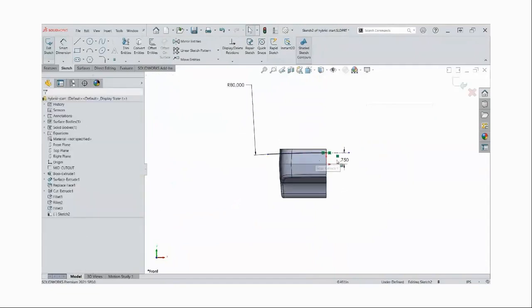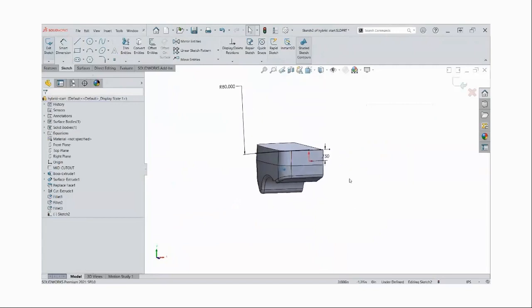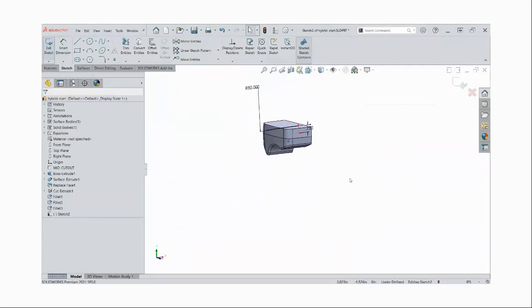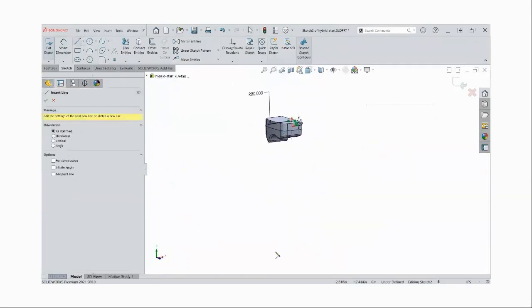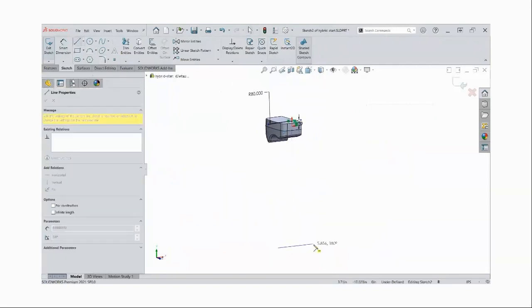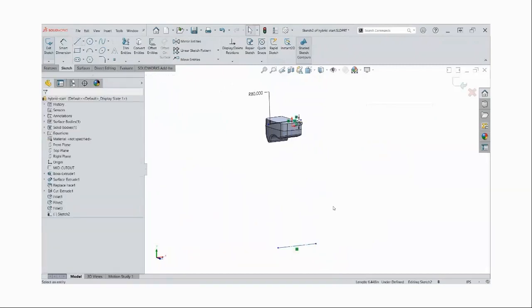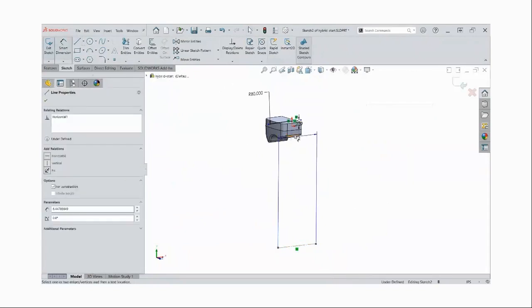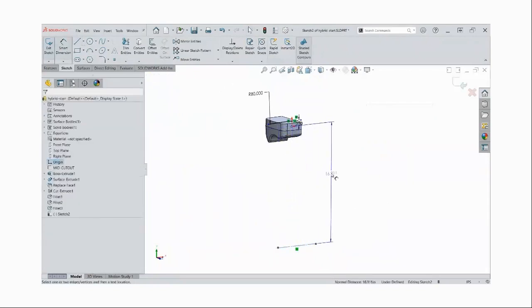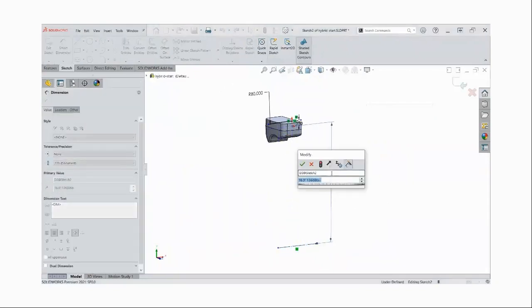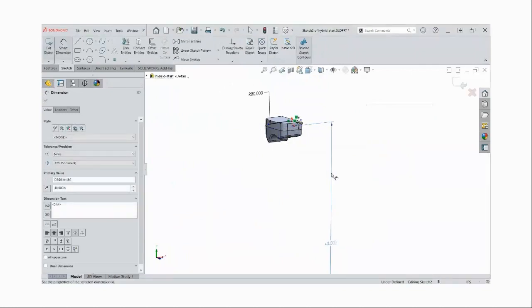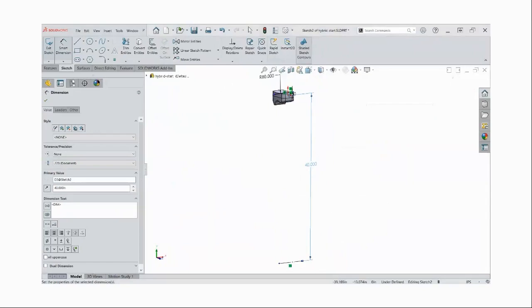And if I just cut that across an extruded cut or something, it would still be flat in one direction. So I'm going to do a revolve. So I'm going to zoom out quite a bit, and I'm going to sketch a revolve axis. A swept surface would be another way to do it if you wanted to go even more detailed. But revolves are a really nice, simple way to produce these shapes. So I'm going to make that 40 inches down. So you can see the revolve axis will be quite a ways down.